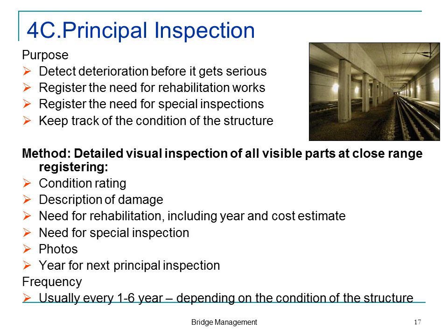If anybody asks me, is there corrosion in this bridge that has been standing for 10 years? My answer would be, yes, of course there's corrosion. And by the way, what bridge are you talking about? Of course there would be corrosion. It would be in a marine environment with salt water, or somewhere where we use de-icing salt. But it's not a problem, unless it seems to get serious. And this is why we do the principal inspections.